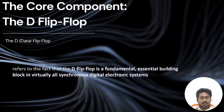And this is the core component, the D flip-flop. The D stands for data. It is a one-bit memory unit. The D flip-flop only changes state when triggered by the clock. The output Q will take on the value of input D only when the clock pulse transitions, for example, on the rising edge.